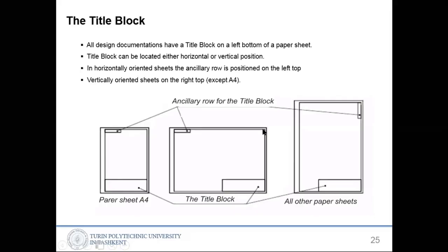For an A3 sheet or bigger, A2, A1, A0, you can do it both ways, in portrait or landscape mode. But for an A4 sheet, you need to use only this positioning, on the small side of the paper.